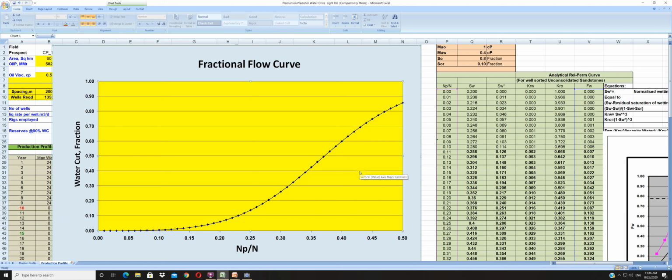I'm seeing some projects coming up very soon in India that in the tertiary stage, a carbon dioxide miscible project will be undertaken, obviously to increase recovery from 40% to 50% plus, and additionally getting some more benefits of carbon sequestration as well. So you can see how to rejuvenate a matured field when the oils are very light and volatile.